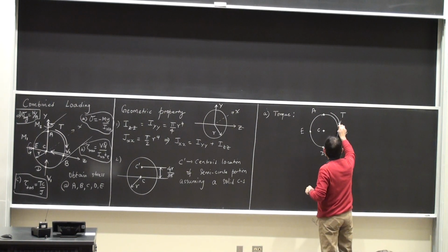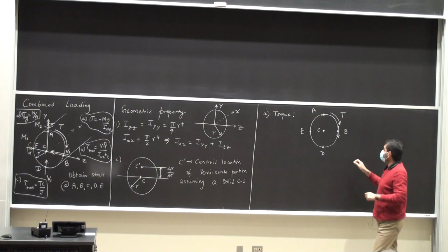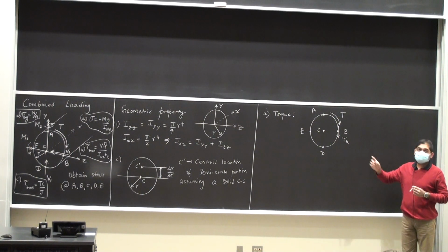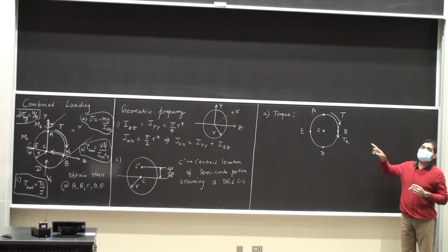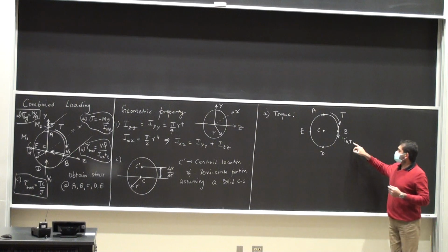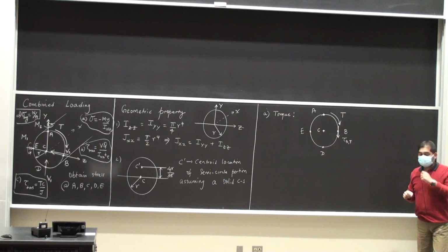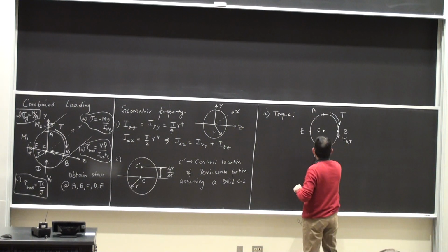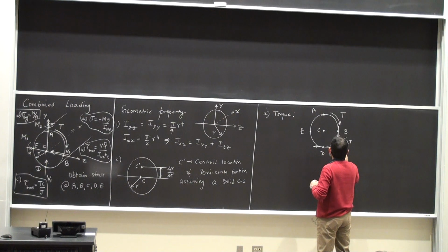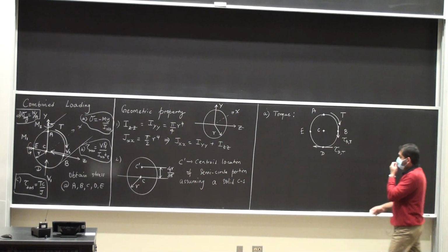Right here, this is going to be the direction of the shear stress, so tau B, and look at my subscript. I'm going to call it as tau B suffix T for the time being. The T representing the fact that this is shear stress caused due to the torque. Okay, then likewise I'm going to do the same thing for each of these points. Tau D at T, then tau E and tau A.